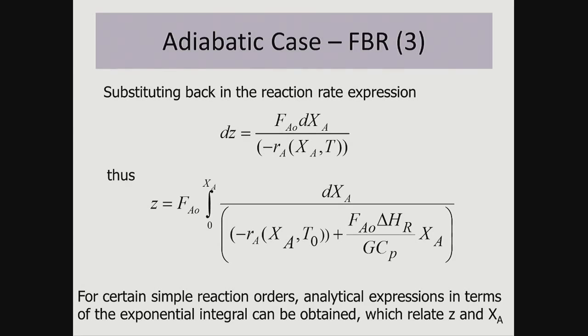Okay, so what we're trying to do is just incrementally calculate the conversion down the bed. If it's exothermic, things will go massively wrong quickly. So if it's a large exotherm, the temperature will spike inside your reactor.